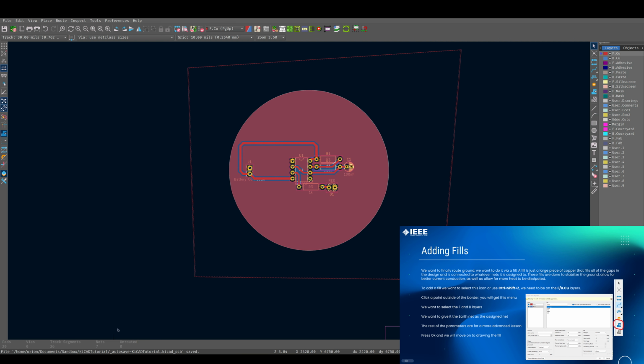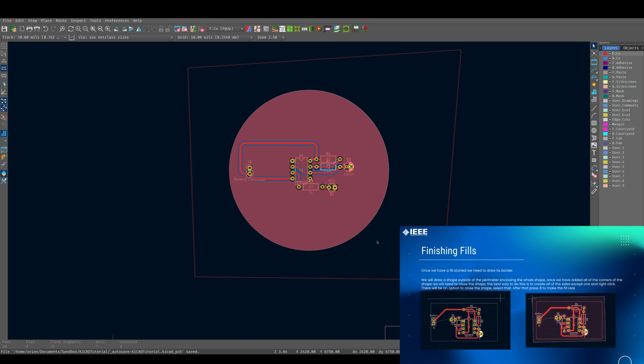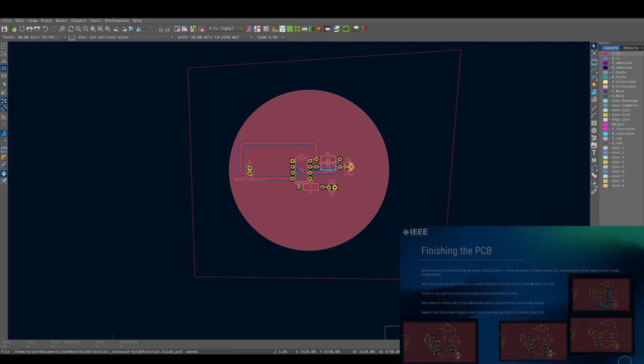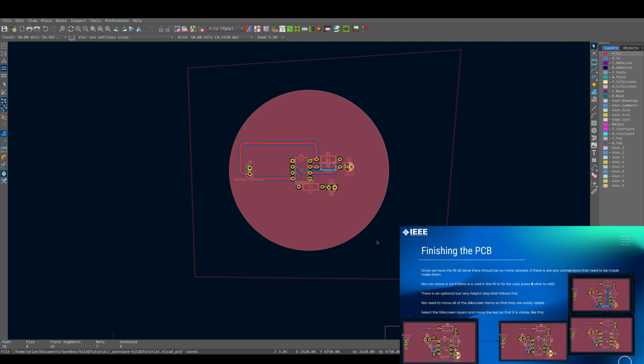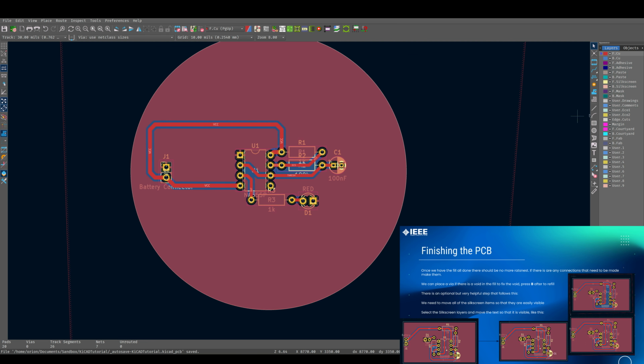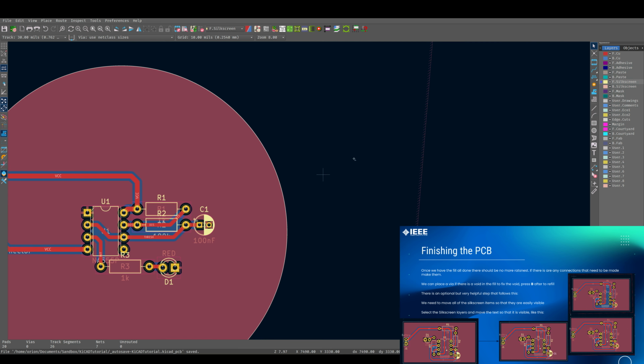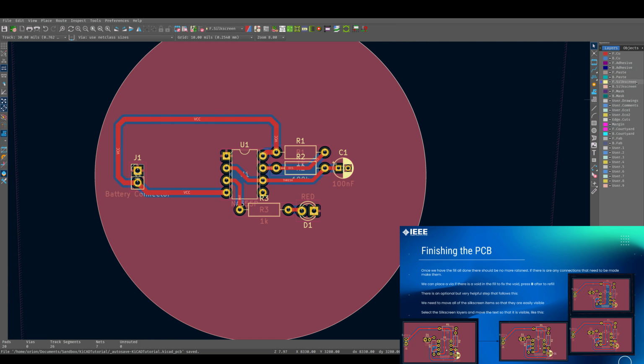That's basically the end of the actual board assembly. The rest is going to be cosmetic stuff, so silkscreen. This is a good example to show how silkscreen works. I click on the silkscreen layer, so I go to the menu, I go to front silkscreen or back silkscreen. In this case, we'll be using front, so front silkscreen.